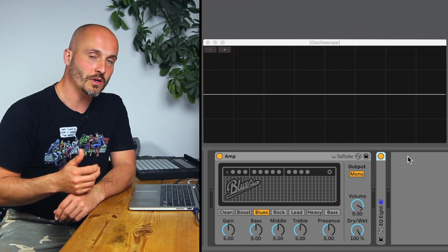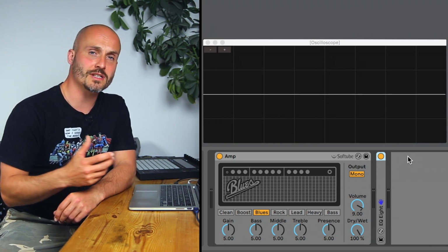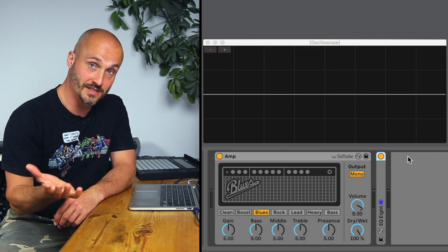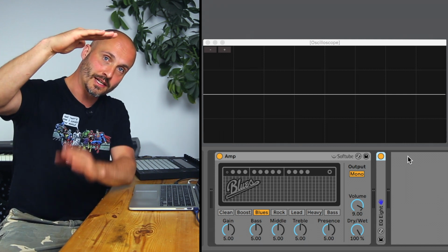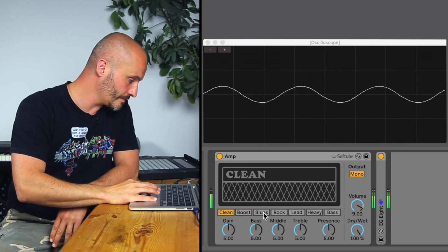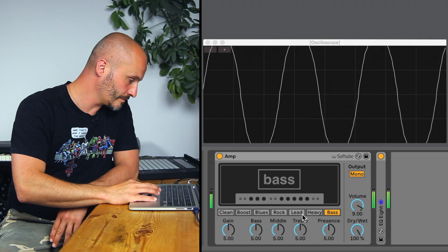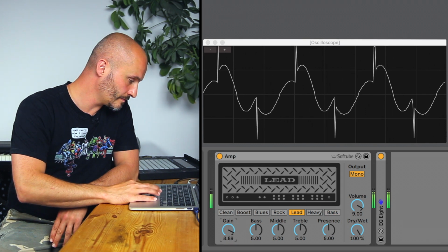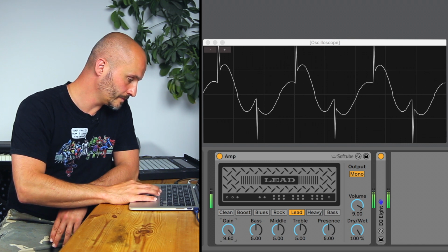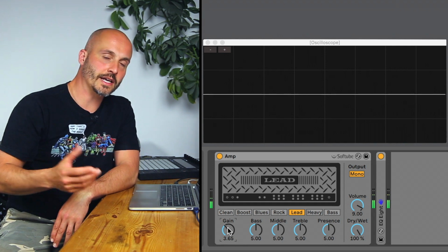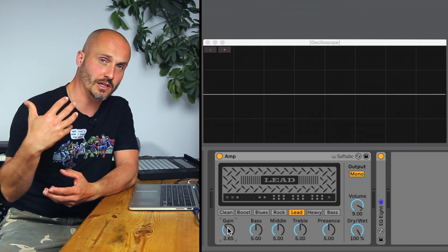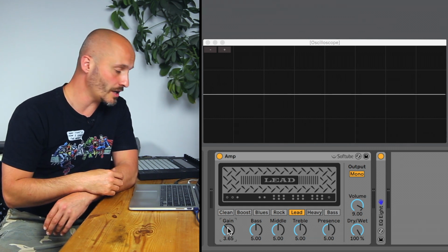So the key things we're looking for when we're using distortion are the distortion type itself, and then the actual input or gain control, which controls how much that signal is getting turned up into that top ceiling and reshaped when it gets to the top. So you can see the gain control can go from just subtle additional harmonics being added all the way to the point where it's very brash, and there's a lot of mid to top information in there.